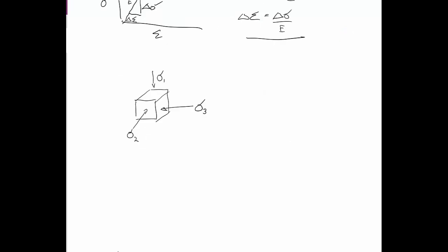Alright, so there's a little soil element sitting somewhere. It has a vertical stress and two lateral stresses acting horizontally. Firstly, we're going to use this as a sign convention. So this pointing downward is positive, and that's positive. Easiest way to think of it is a sponge. I'm just going to work in 2 dimensions.